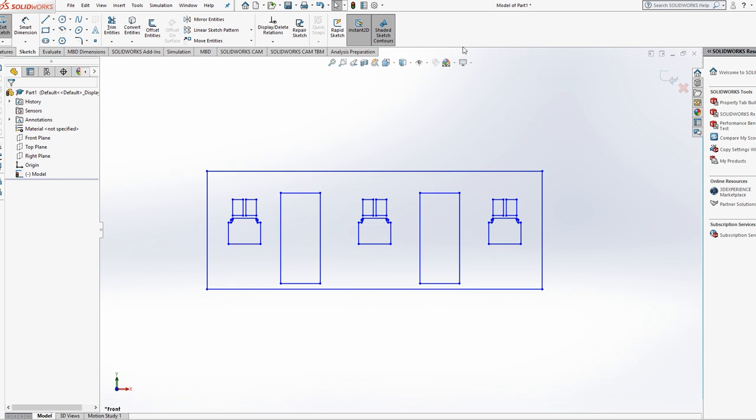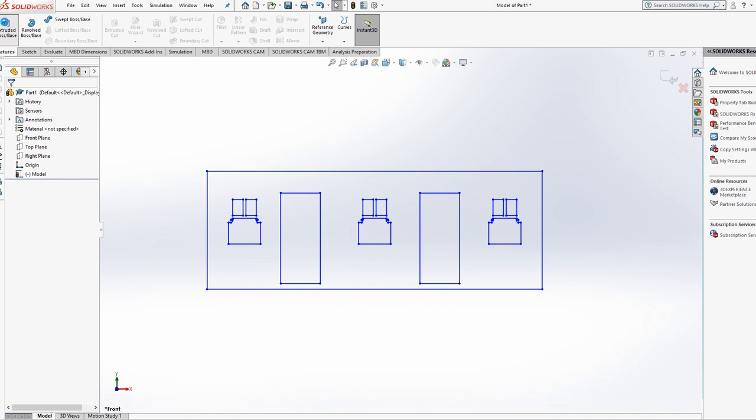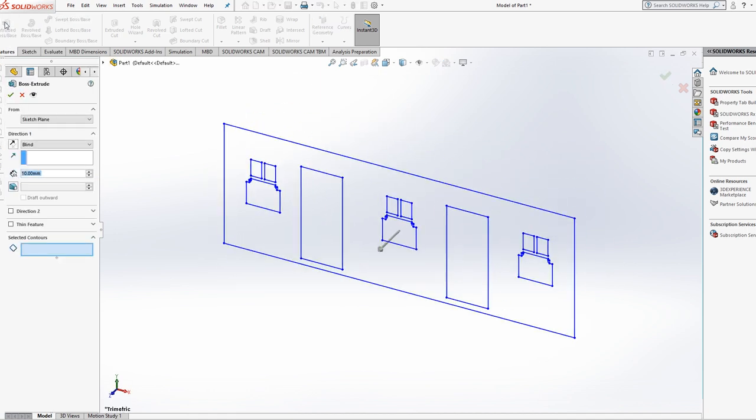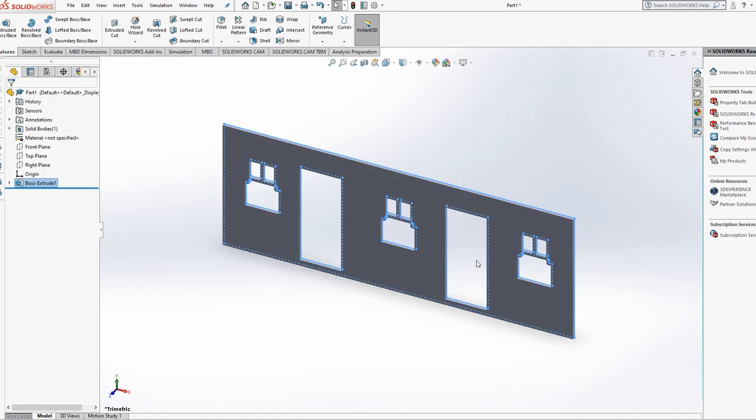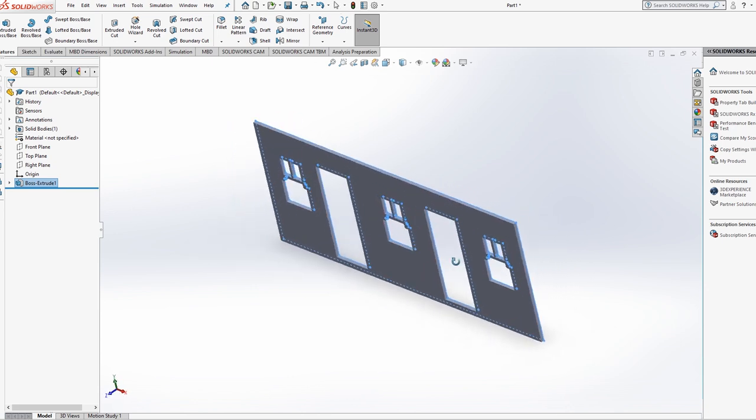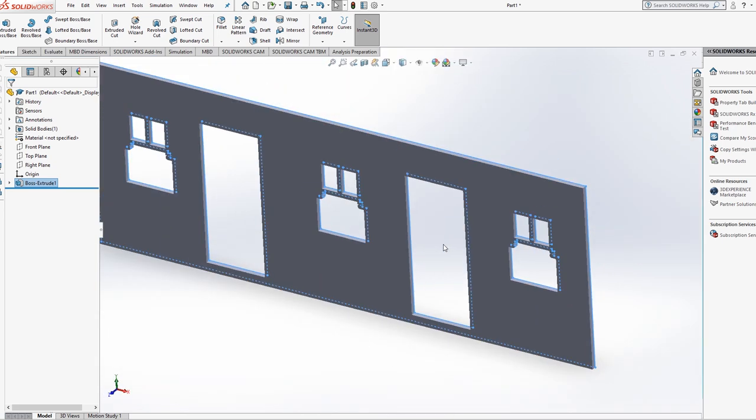Now I must explain here that I'm using, should be obvious, but I'm using 3D software. I'm actually using SolidWorks. Now, having got that 2D profile, I can extrude that using the extrude tool. And if I enter in this box on the left, 1 millimeter, there we go, that has now given that 1 millimeter thickness.